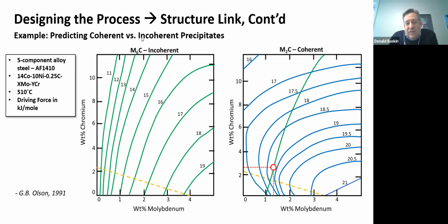So when you take a tube of Reynolds 853 and you braze or weld it to another tube, and Tom can help me with this because he's a welding expert here, you can turn some of that material in the weld zone to austenite, I think. And then if you quench it, it'll form martensite. If you air quench it with 853, it'll still form martensite. It's an air hardening steel. But it's untempered martensite, so you have to temper it afterwards.